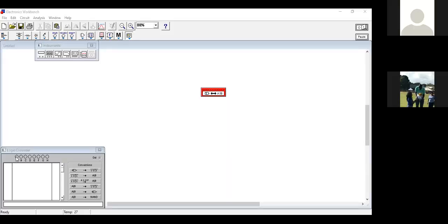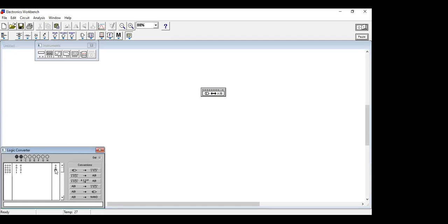All right, so we put in the truth table, and it's 0. Click on the next one, it would be 1. Or if you double click on it, it's supposed to change. Now you can just type in the X, 1, and then we simplify it. And you see the simplification. You see what I'm typing on the screen, the simplification is down here. That would just equate to B alone. Yes, I'm seeing it. Okay.